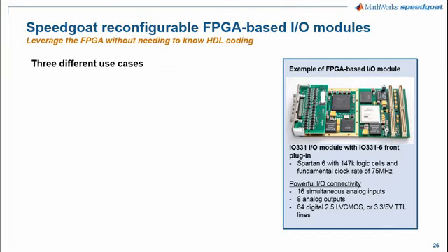Thank you, Brad, for the demonstration. This demo leverages a powerful FPGA-based I/O module for PWM generation and encoder capture. Megahertz granularity is needed to adequately cope with PWM and encoder signals, and the FPGA is the perfect candidate for this task. The card used offers digital and analog I/O connectivity and is therefore ideal for motor control applications.